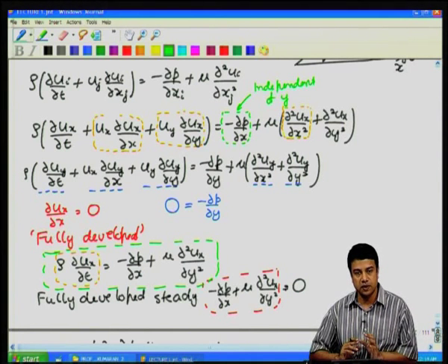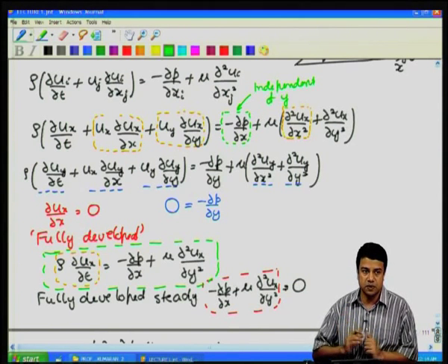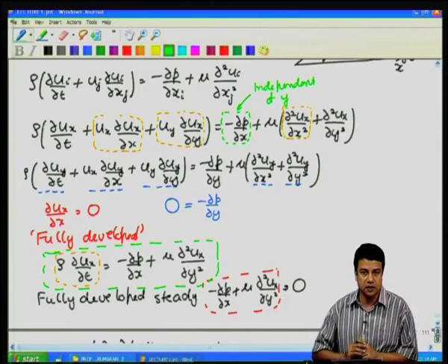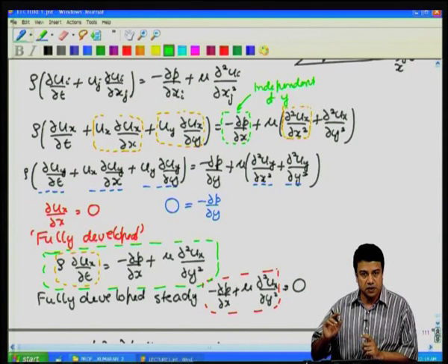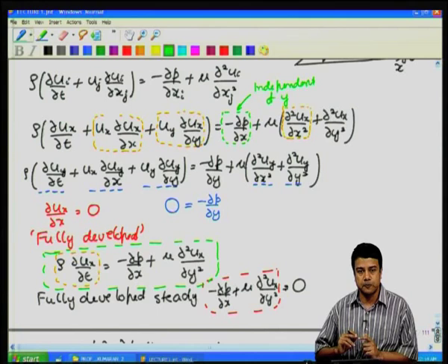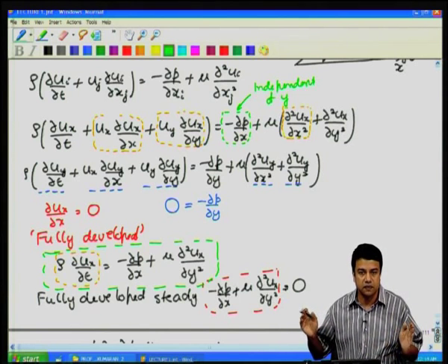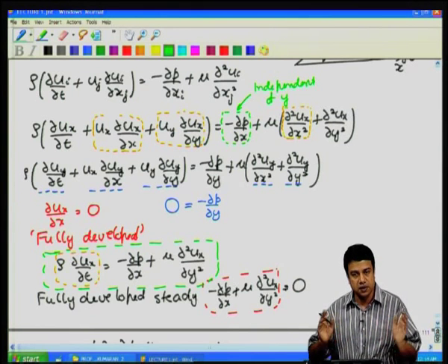In that limit, you will get boundary layer solutions at the wall, and the flow near the center will be a plug flow. In that case, the flow is fully developed, no variation in x, but it is not steady. It depends upon time. That is because the pressure difference applied across the two ends is time dependent.